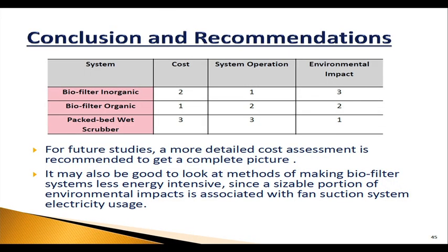So there are different systems out there, as you can see: biofilter inorganic, organic, and packed bed scrubber. And you have to look at the cost. See, environmental impact is a very, very important parameter. This whole exercise of LCA is to find out the environmental impact. So whatever data you see over here is based on the LCA exercise, where we got the packed bed wet scrubber as number 1, then biofilter organic as 2, and biofilter inorganic as 3 in terms of the ranking.